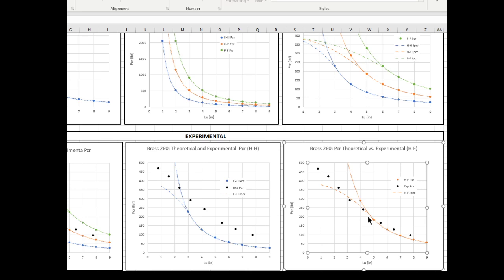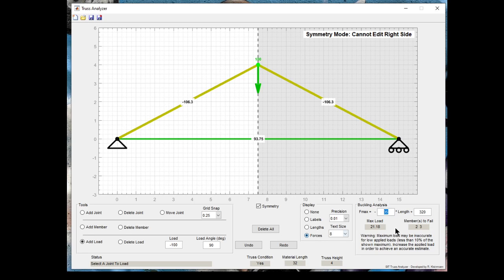The problem with that, for example, is it looks like this data is closer to hinge fixed, and we know from our simple planar truss theory that trusses need to have hinged connections. So what would we do with that? We need to think about that. But also, it shouldn't be linear. Neither of our theoretical calculations have linear trend lines. And so just applying a linear trend line to the data is kind of a lame way of doing it. So that's why I don't use this equation in my sections. Your professors may say something different if you're in different sections and you're watching this, so pay attention to them.